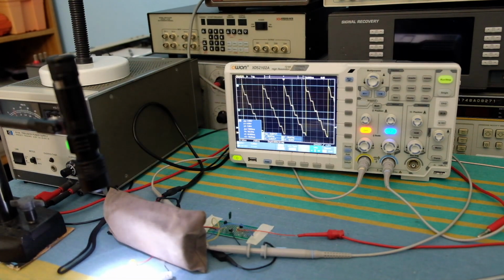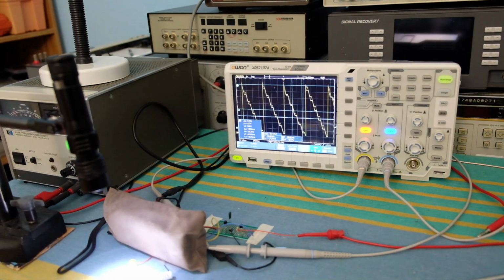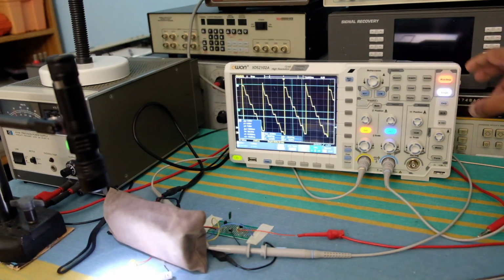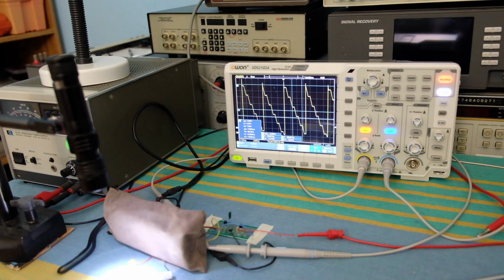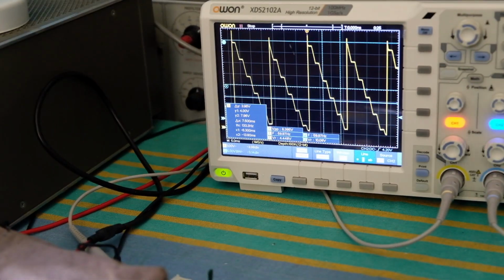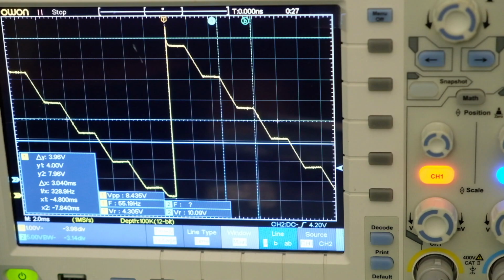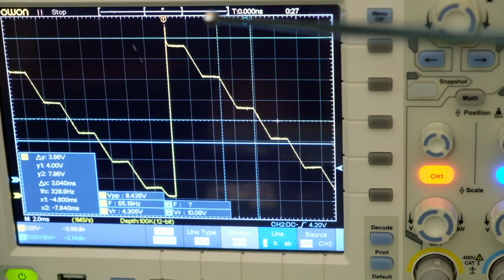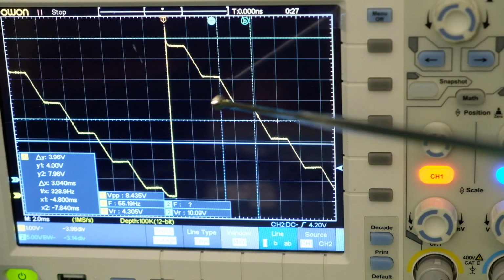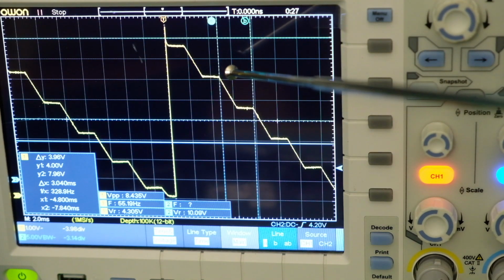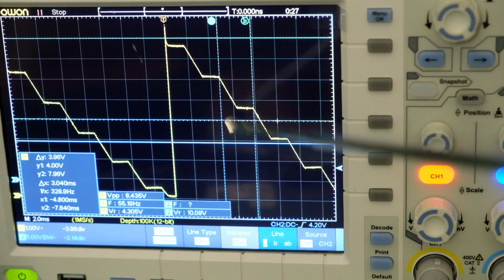That modulation is measurable, and I can do that by stopping the trace over here and then measuring the distance of that jagged pulse coming out. So what I'm going to do is measure that and come up with the frequency at which this is being modulated. Here's a little better close-up of that waveform, and you can see this stair-step effect is the modulation that's going on, stopping the light and then allowing the light to go through, which effectively dims the flashlight.